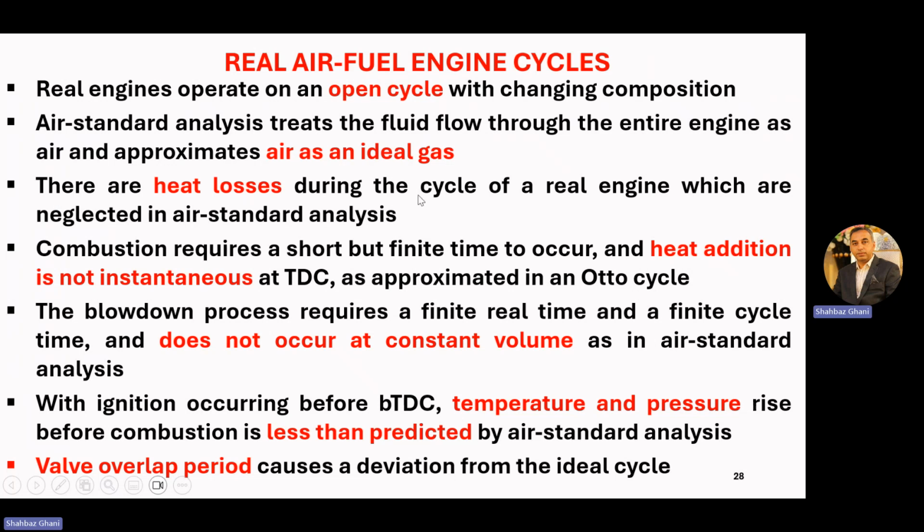There are heat losses during the cycle of a real engine, which are neglected in the air standard analysis. Combustion requires a short but finite time to occur, and heat addition is not instantaneous at TDC as approximated in an Otto cycle. So these are a few comparison points.